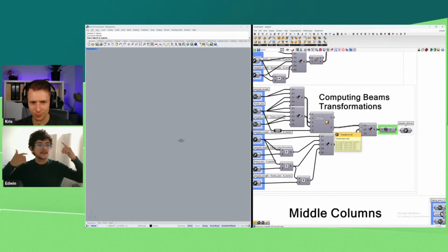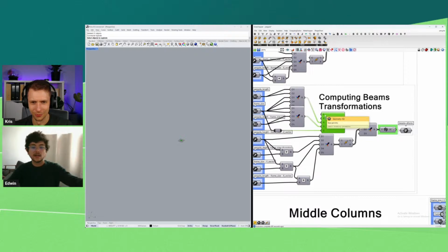You have to do it implicitly, or you could do it explicitly if it's difficult to do implicitly in your mind. Just imagine that you are explicitly transforming your cube, no? That means the best is to do it at the origin. Because otherwise, if you do it off the origin, that transformation is also going to apply to the position of your geometry with respect to the origin. So it's better to do it from the origin, so first I scale, then I move wherever I need.